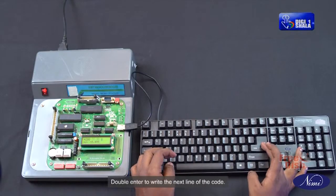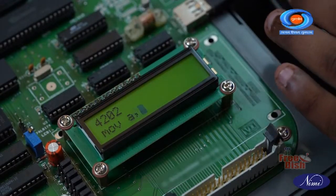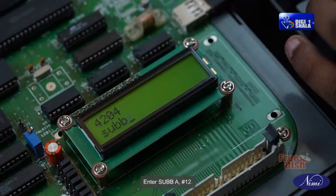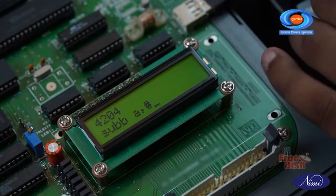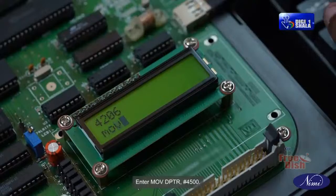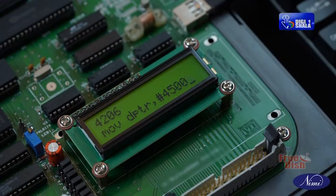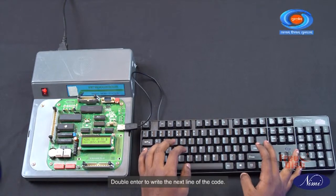Double enter to write the next line of the code. Enter MOV A, #25. This moves the 8-bit number 25 to the accumulator A. Enter SUBB A, #12, subtracting the 8-bit number 12 from the value currently in the accumulator. Enter MOV DPTR, #4500. We are assigning the data pointer register with an immediate value of 4500. In this address, the output will be stored. Double enter to write the next line of the code.